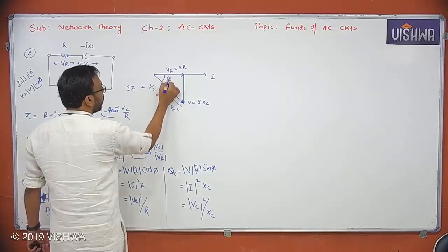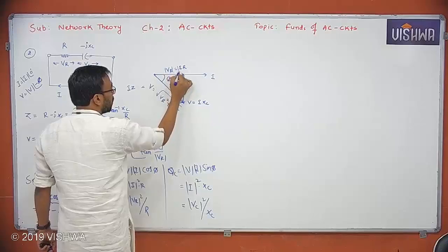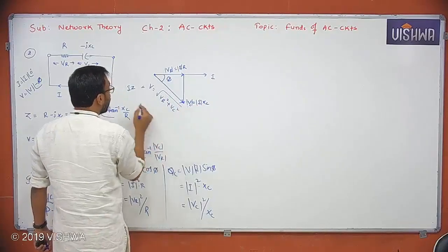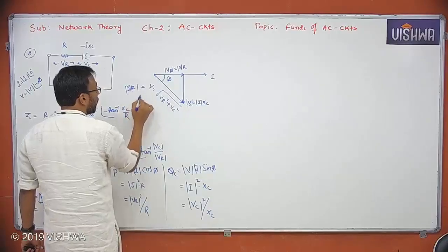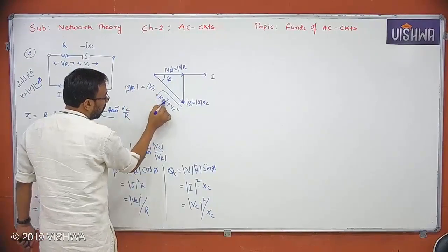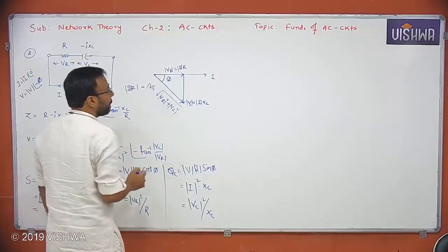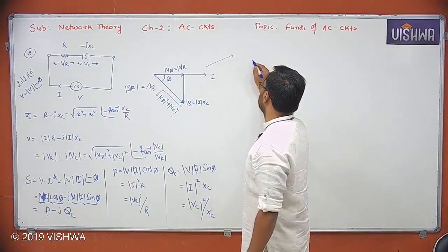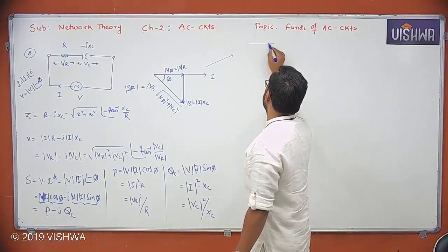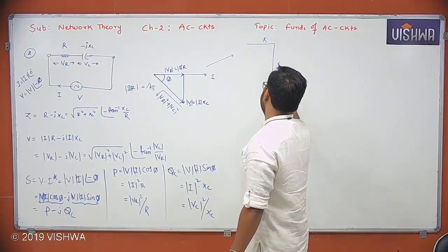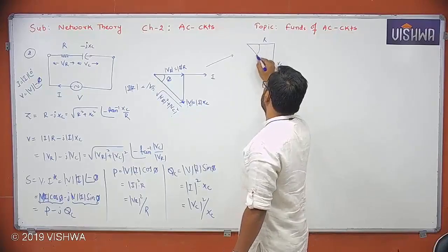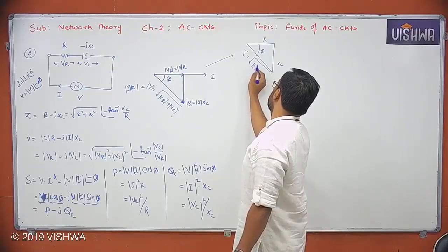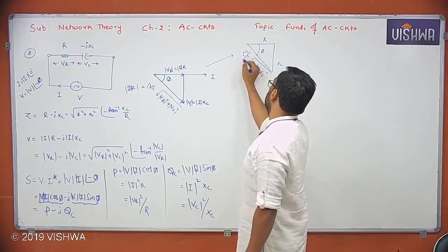Okay, this is phi. These are all magnitudes. Okay, I may not write sometimes, but you must be understanding that these are all magnitudes. You're dealing with magnitudes. Don't forget that. All are magnitudes. That's it. Okay. Now here, if I take multiplying each phasor by I, then this is R, this is XC, this is phi. Z is equal to root of R square plus XC square. Okay.